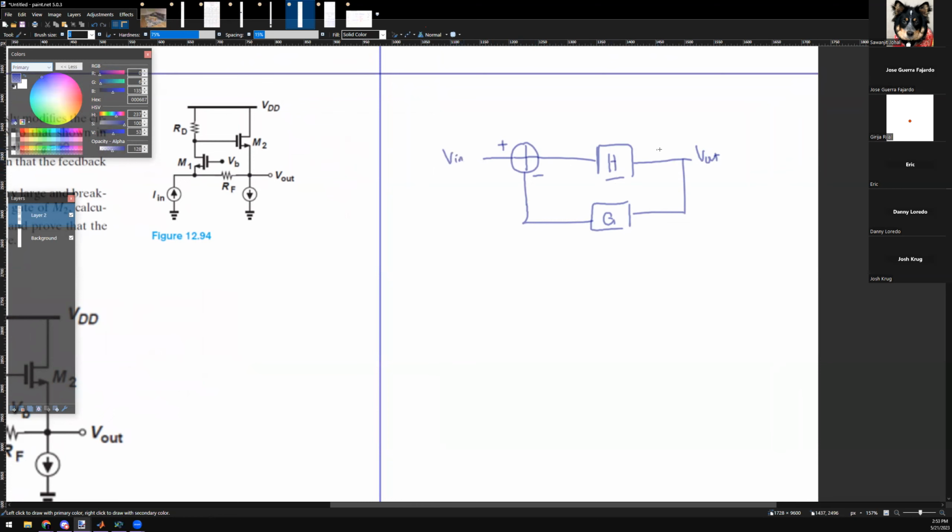The way you prove negative feedback is that if V out goes up, this terminal goes up. If this increases, this terminal goes down, which counteracts V out and it goes down. So once I go through any perturbation in the loop, what you originally assumed gets counteracted. I originally assumed an increase and I get slapped down with this final result.